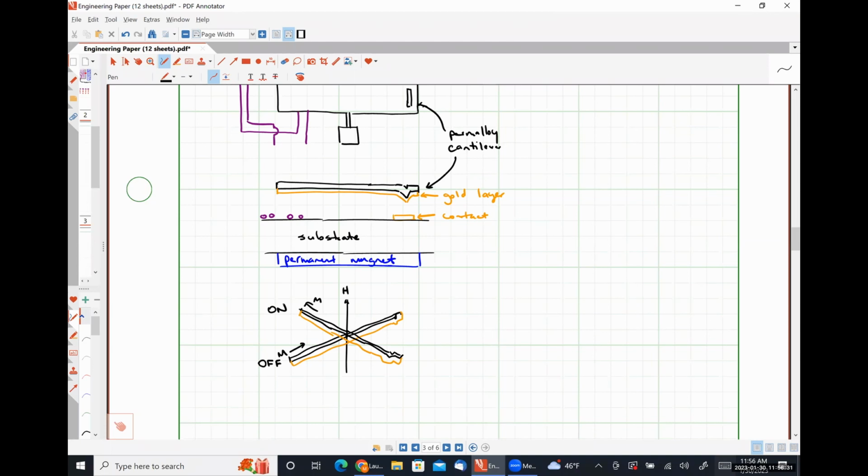So it's the attraction between the permanent magnet and the magnetization of the cantilever itself that's causing it to stay closed, so that it doesn't require power to keep the switch closed. When we talk about electrostatic switching, when we get into talking about RF MEMS, one of the biggest problems with that is that the switch only stays closed when you're supplying power to keep it closed, right? So you only need power if you want to change the state.